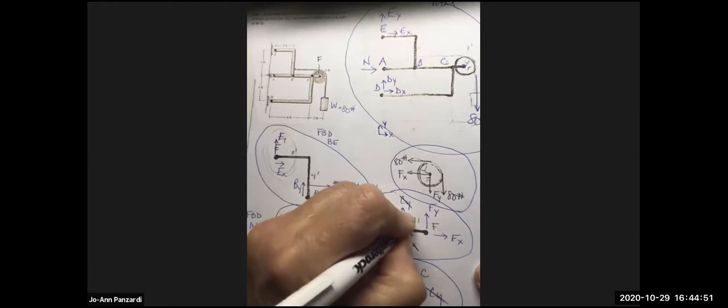Wouldn't it? Well, let's not talk about tension and compression, okay? I prefer not to talk about that because we're going to get to that in trusses. So just call it, is it up to the left, up to the right, down to the right, down to the left? Up to the right. So I have to draw it up to the right because it's equal and opposite at this point C. And we could probably do that if we're going to reduce the other one, EB, AB. Right, so here we have a DX and DY, so we have to reduce that too.